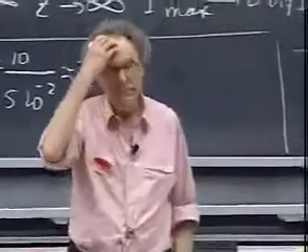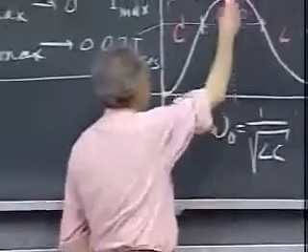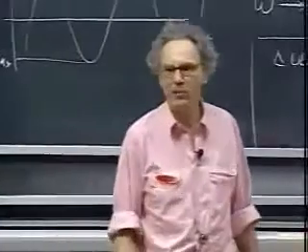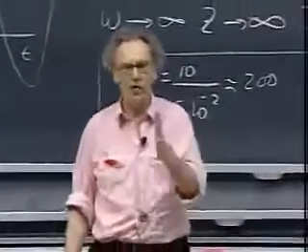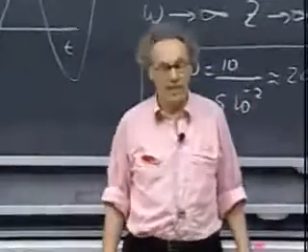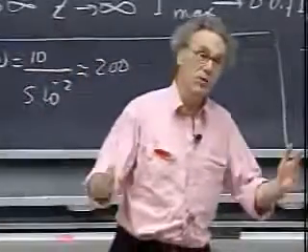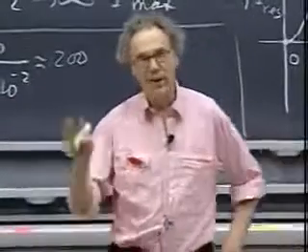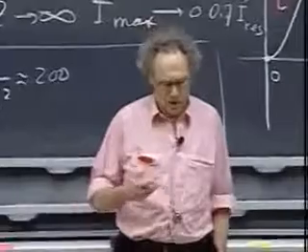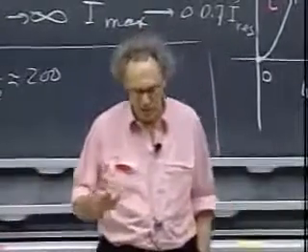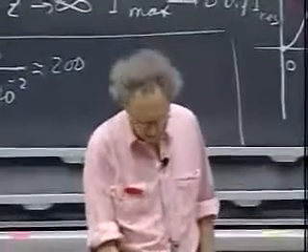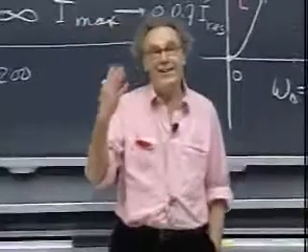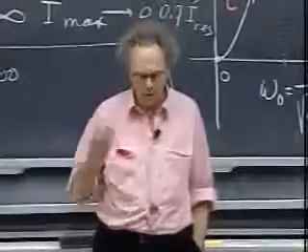Resonance can be destructive. Imagine if you have a very high Q system. If you're slightly off resonance, there's almost no current, no power dissipated in your resistor, and now you come all of a sudden on resonance, you get an enormous current, and that means there's an enormous power dissipation in your resistor, and you can burn out your resistor. You can destroy your circuits if you're not careful. In the next lecture and Monday, I will also discuss with you some mechanical resonances. Mechanical systems can also go into resonance. They can also be destructive. At certain frequencies, the systems behave, call it violently, they respond extremely strongly to their input frequency, and things can break.